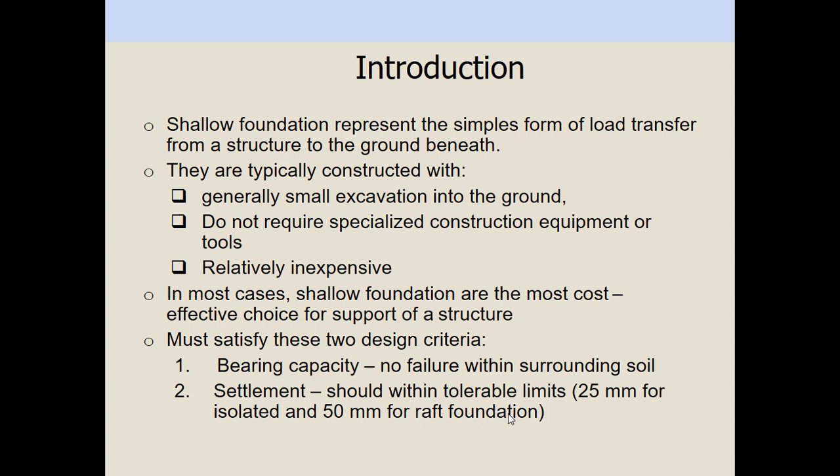So the shallow foundation. What is a shallow foundation? A shallow foundation represents the simple form of load transfer from a structure to the ground beneath. They are typically constructed with generally small excavation into the ground and do not require specialized construction equipment or tools. Maybe we need only the excavator, right? You have to dig the hole, maybe 2 meters, maybe 3 meters, or maybe 4 meters.